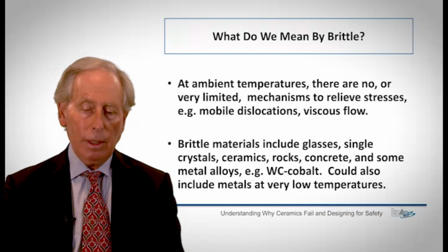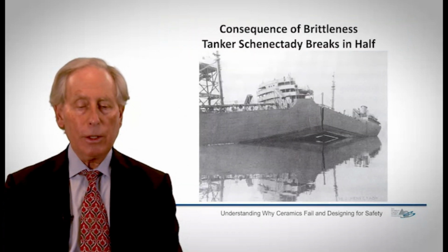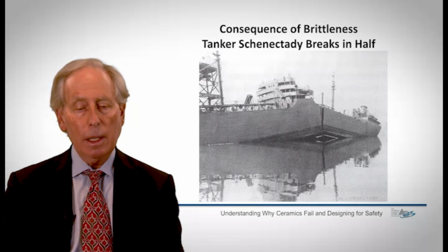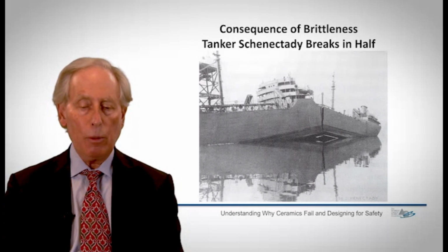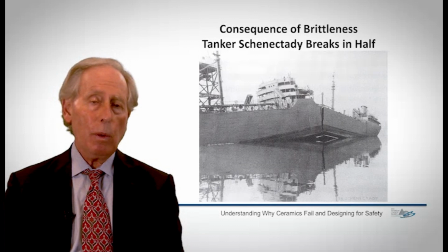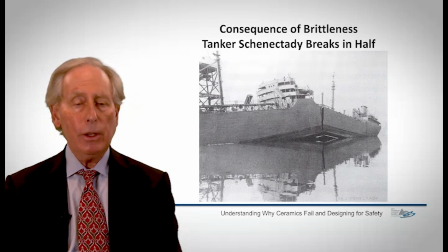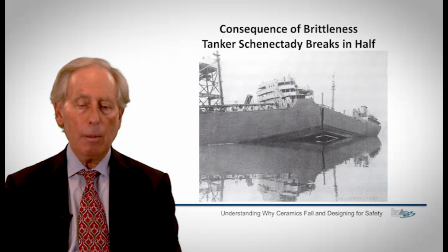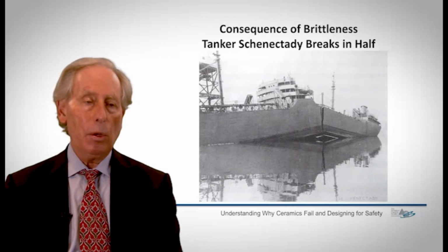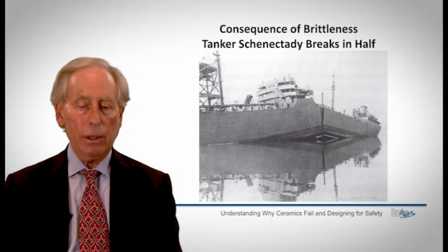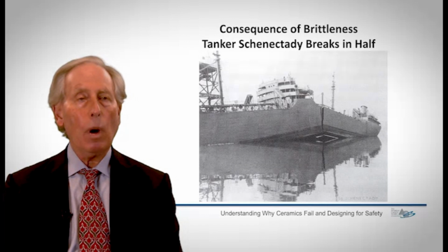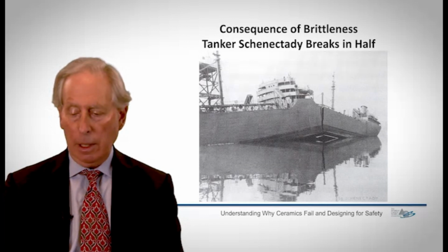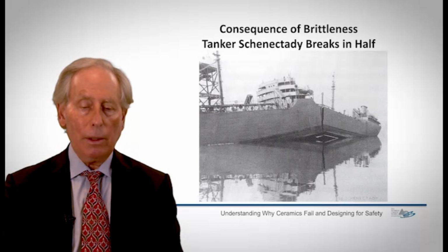And the application that's usually shown is this picture of the tanker Schenectady in the 1940s, which was sitting in harbor, and in very cold water, that metal, the steel in the ship, became brittle, and the ship simply broke in half. And this was one of the motivations for the instigation of studies at the Naval Research Laboratory at the time into brittle failure, and some of you might have heard of Dr. George Irwin there, who is really considered the father of fracture mechanics. And this is really some of the reasons why fracture mechanics became so important, to understand why brittle failure occurs under some conditions. And you'll hear more about this, or a lot more about this later on.